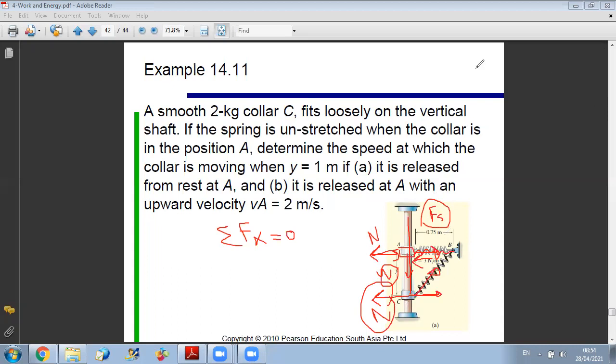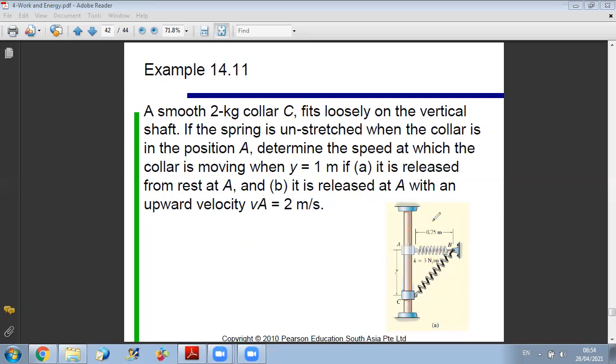The principle of work and energy is always applicable, okay? But the principle of conservation of mechanical energy is only applicable in case all forces doing work are conservative. So here, since this condition is satisfied, I can apply the conservation of mechanical energy. I have two types of potential energy here: the gravitational potential and the elastic potential. So I will consider the mechanical energy conservation between position A and position C.